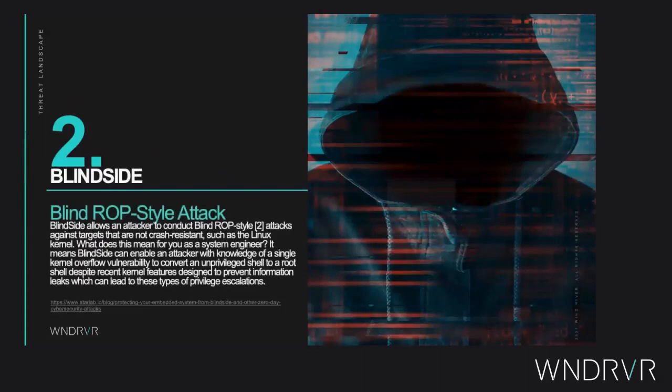Next, we have Blindside. Blindside is the ability of an attacker to take over a system. So it uses a single known kernel vulnerability and allows the attacker to get access and then elevate their privileges up to admin or root access. And if you know and understand a Linux-based system, if you can get root access on a system, you pretty much have unfettered access and can do anything that you want to do on that system. So another extremely dangerous attack against your embedded system.